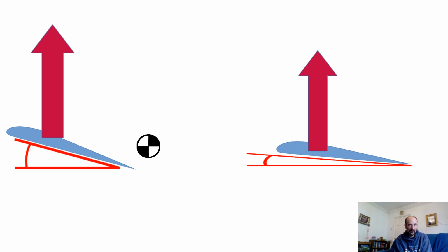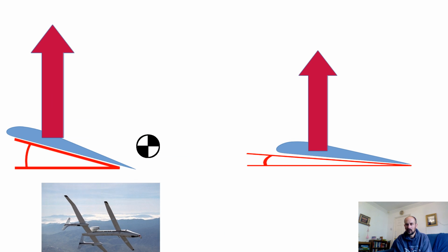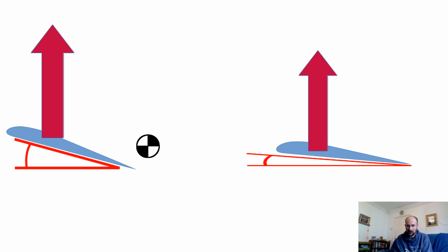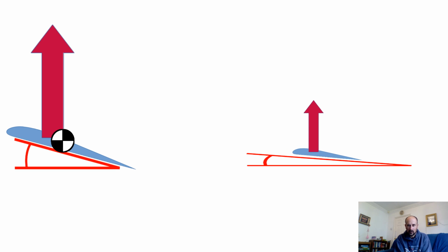And this will also be a stable aircraft, so there's examples of tandem wing aircraft too. And then if we were to take this tandem wing and shrink down the tail so that the rear wing is smaller than the front wing, of course we're back to our conventional aircraft, but at some point we'll get to a stage where the rear wing is somewhat smaller than the front wing. It can still be generating lift, so your tailplane can still be a lifting surface as well as the main surface.